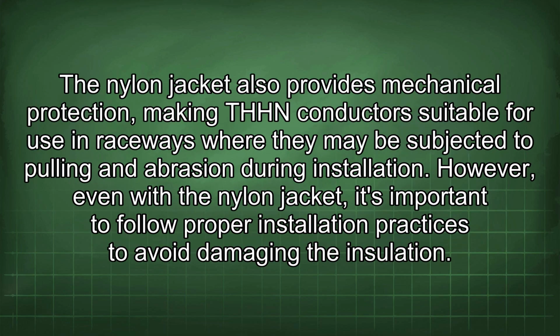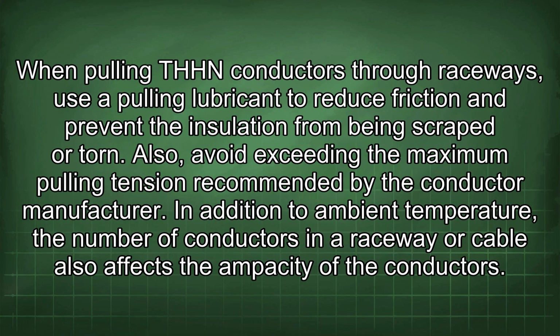The nylon jacket also provides mechanical protection, making THHN conductors suitable for use in raceways where they may be subjected to pulling and abrasion during installation. However, even with the nylon jacket, it's important to follow proper installation practices to avoid damaging the insulation. When pulling THHN conductors through raceways, use a pulling lubricant to reduce friction and prevent the insulation from being scraped or torn. Also, avoid exceeding the maximum pulling tension recommended by the conductor manufacturer.